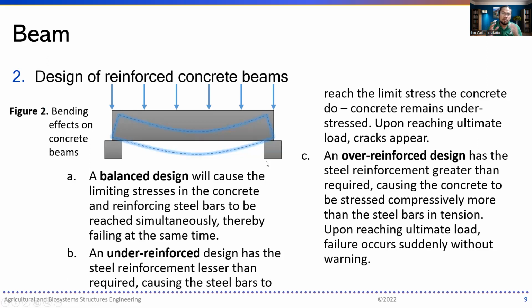Now, wood is done. We have now the reinforced concrete beams, and we have reinforced concrete beams because concrete, while it is a very good and very cheap material in construction, has a tensile strength of 0. Thus, it is important to reinforce the concrete with steel because the concrete attaches completely to the steel.